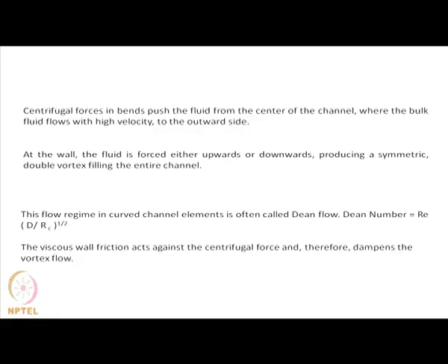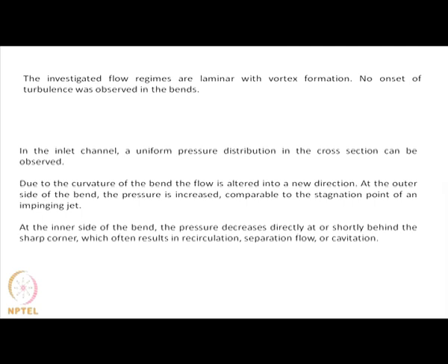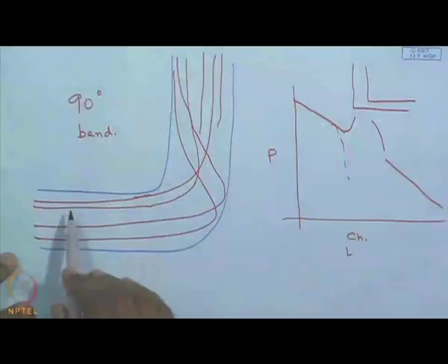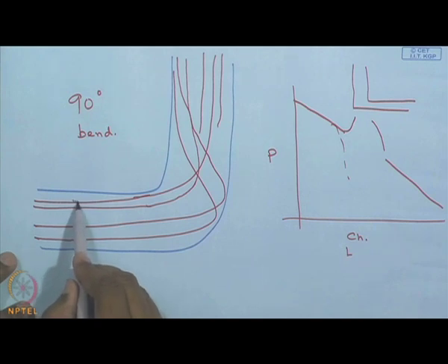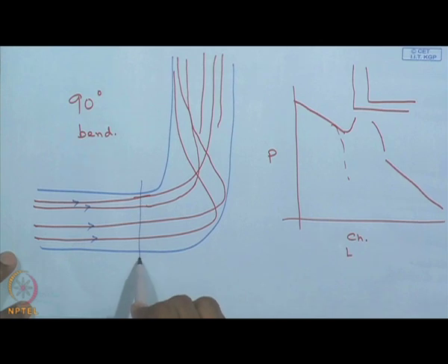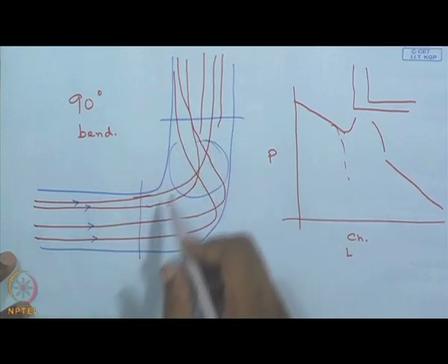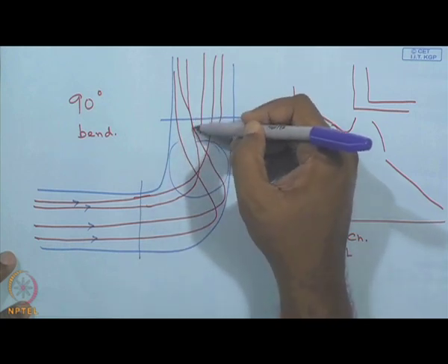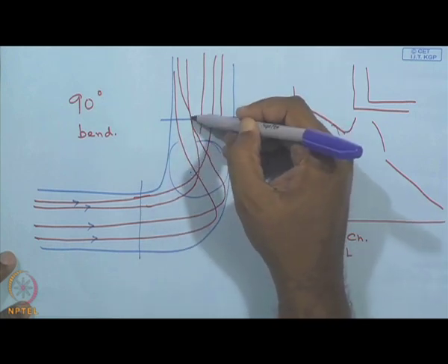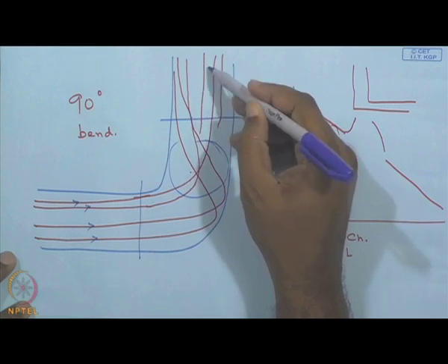So now let's say we move to a situation in which there is a 90-degree bend, and at this 90-degree bend what we see is that the straight streamline of the flow before the bend suddenly gets mixed in this region, and then afterwards, once we go far from the bend, the flow becomes stabilized again.